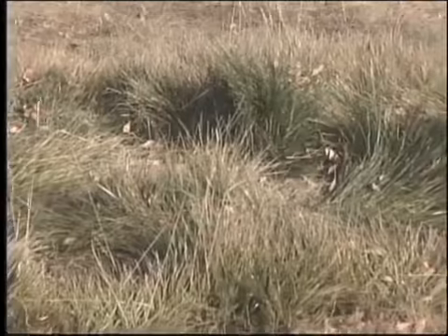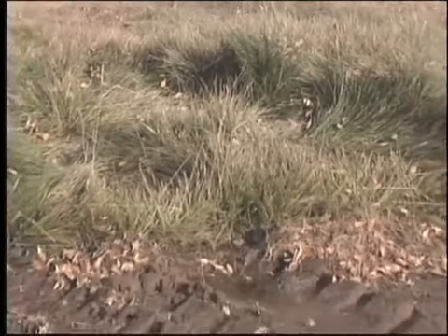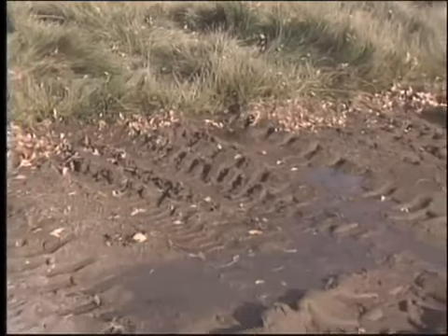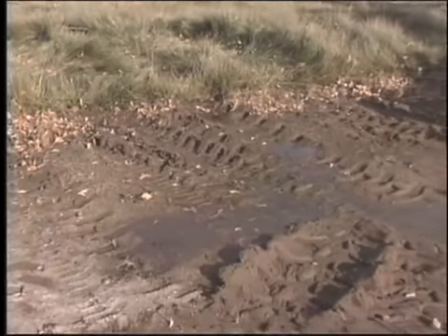The first compartment is so important that there is a backup compartment to ensure that the septic tank doesn't fail in doing its job. If the tank should fail to retain the grease and solids, the drain field will become plugged, and the partially treated sewage will surface where family members may be exposed to the disease-carrying bacteria.